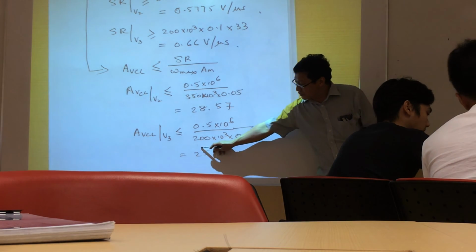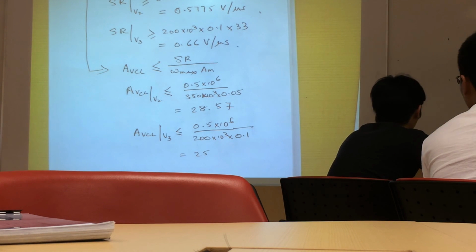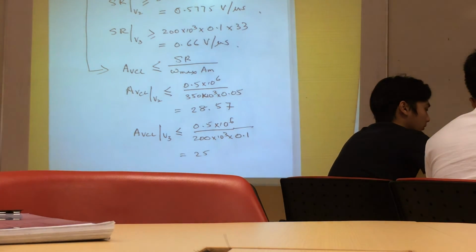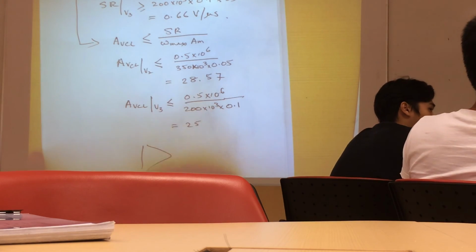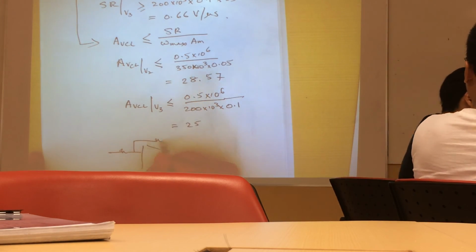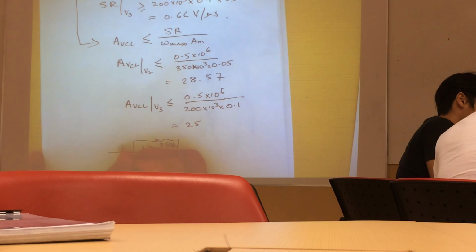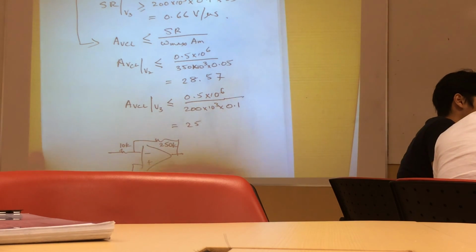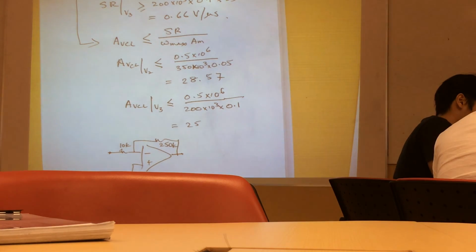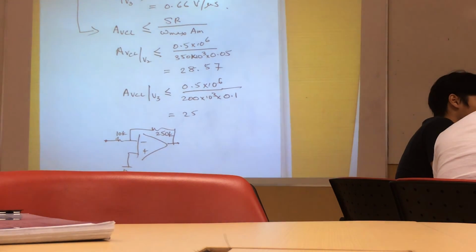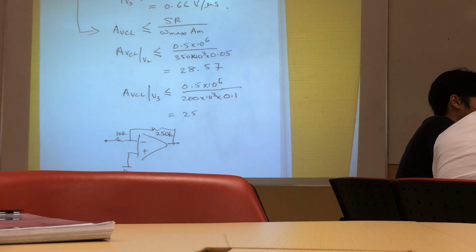So therefore, all you need is to change the resistor, and in this case, we can change the resistor so that the amplifier looks like this. 250K, 10K, and you'll be able to get a gain of 25. Right? Instead of 330K, now you swap it to 250K. Then all four signals will come in and go out undistorted with the gain of 25. Okay? Any question?